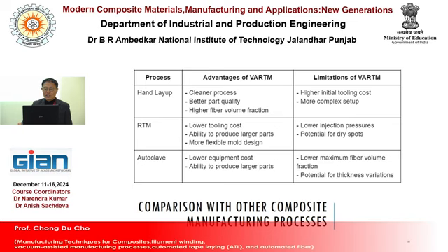VARTM is a cleaner process, better part quality is possible, and higher fiber volume fraction. But compared to hand layup, VARTM must have a higher initial tooling cost, and a more complex setup.